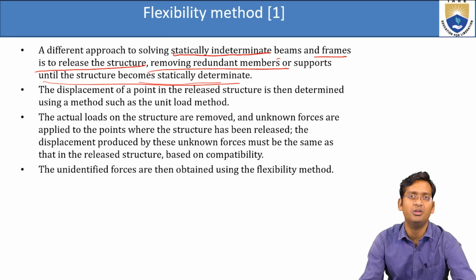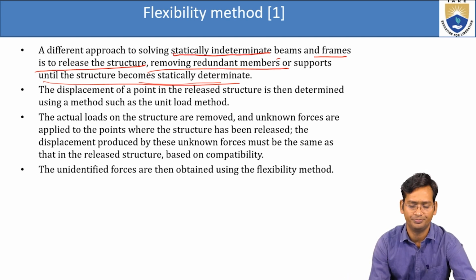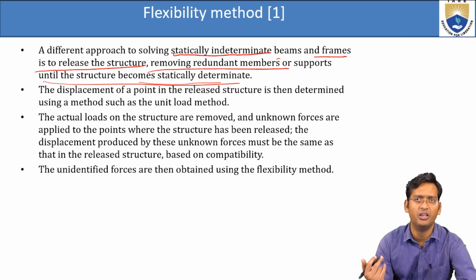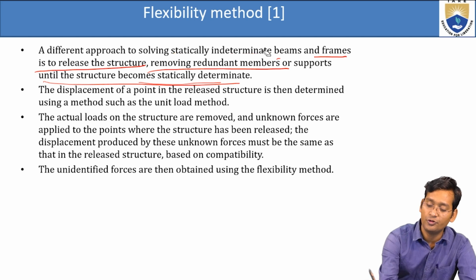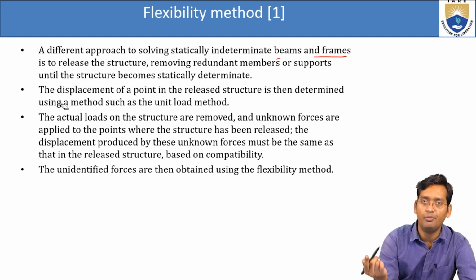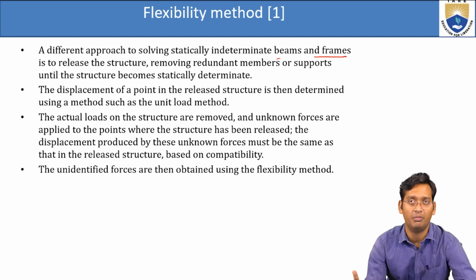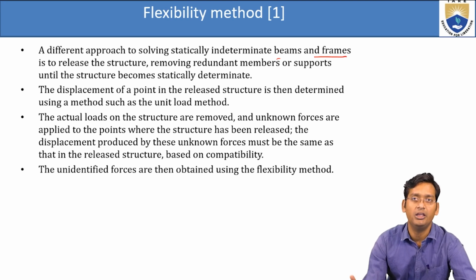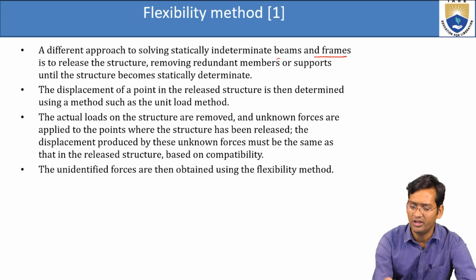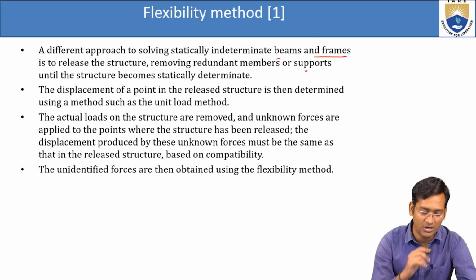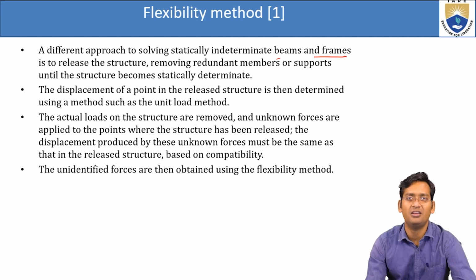Now, once it's statically determinate, you can apply any method: either the unit load method, total potential energy method, or Rayleigh-Ritz method, any method. The only thing is, first, for the complex structure, you have to make the indeterminate structure determinate by removing the redundant members, which do not carry or contribute any load. Start removing those members. Once it becomes a determinate structure, then it's easy. Now you can go for any other method.